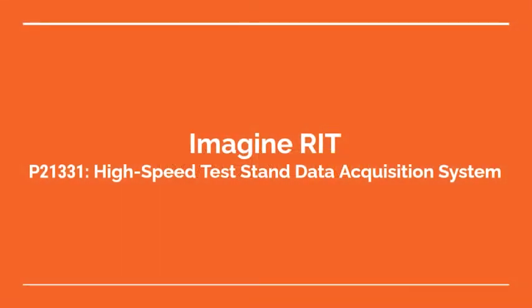The P21331 MSD project involves the design of a high-speed data acquisition system, better known as a DAC, for rocket engine testing. Our DAC is capable of measuring acceleration and vibration using IEPEs, applied forces using load cells, temperature using thermocouples, and additional sensor types using a robust current loop protocol.